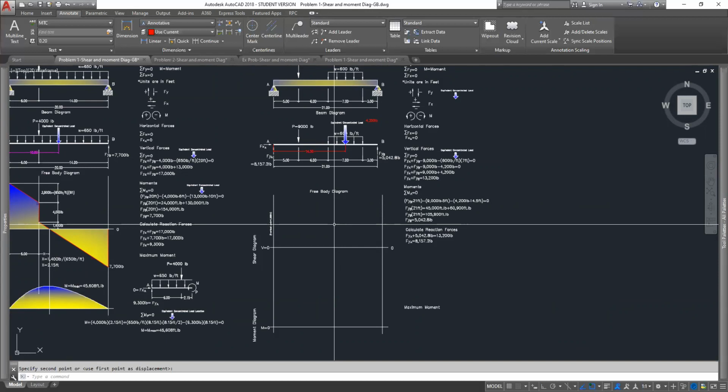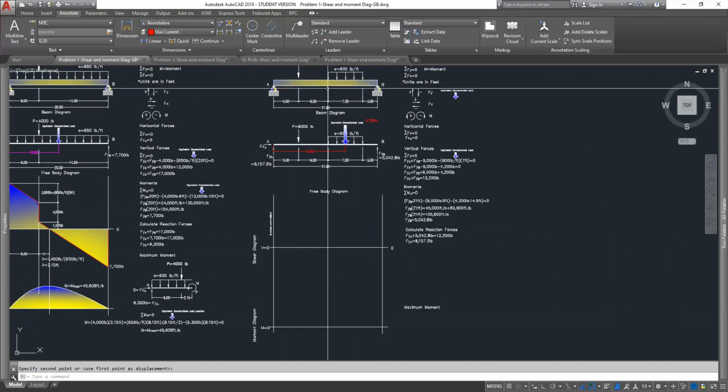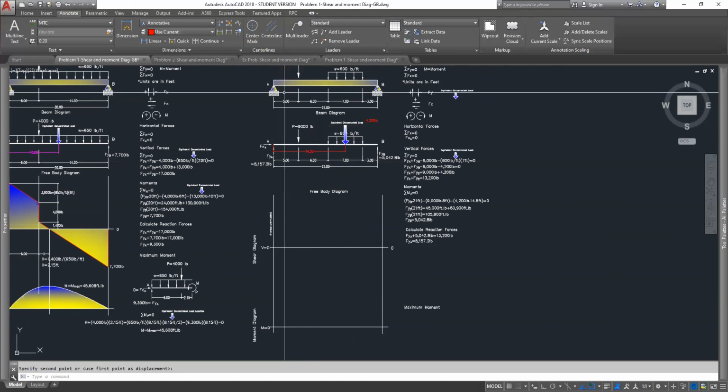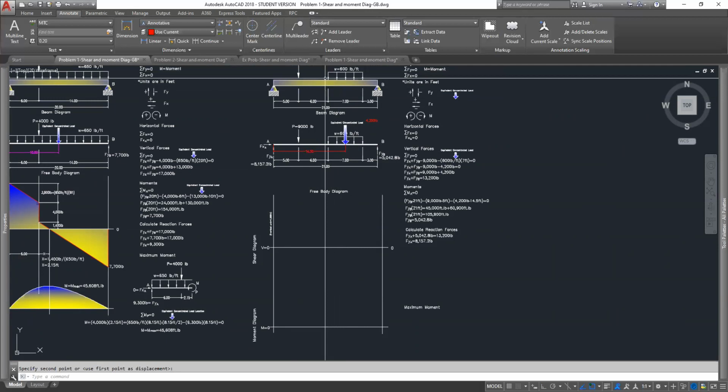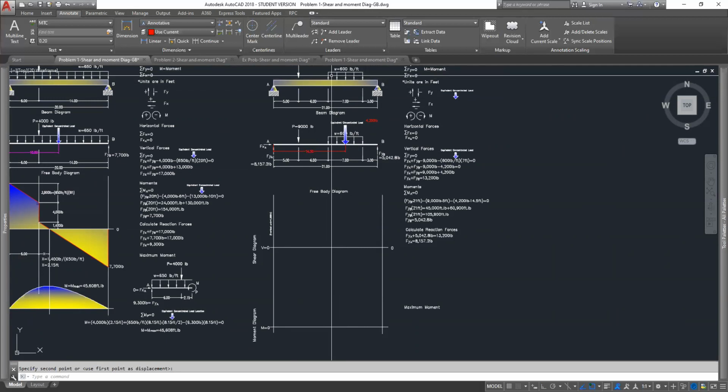In wood, it depends on whether it's with the grain or against the grain. In steel and in concrete, it's a little bit different. But this is the process that engineers use to analyze beams and determine the size of the beam and whether it can span the distances you're trying to cover. So if we have a span of 21 feet, let's determine based on the loads coming onto it, and that's going to be the next assignment, having to do with the codes and tables for applying loads.